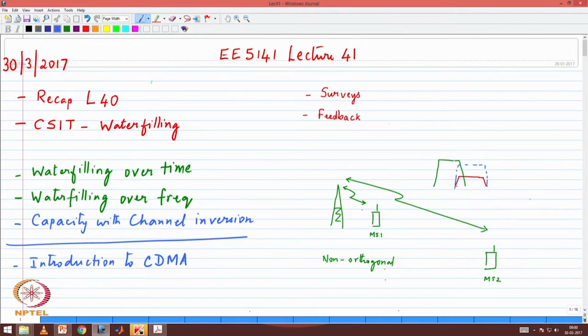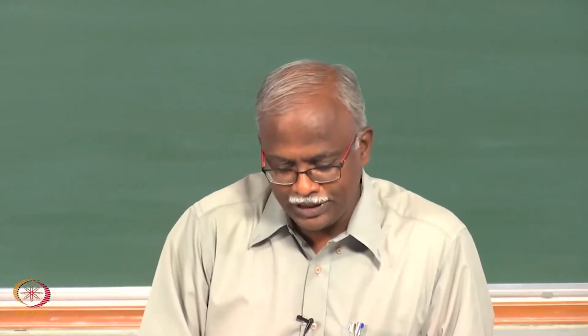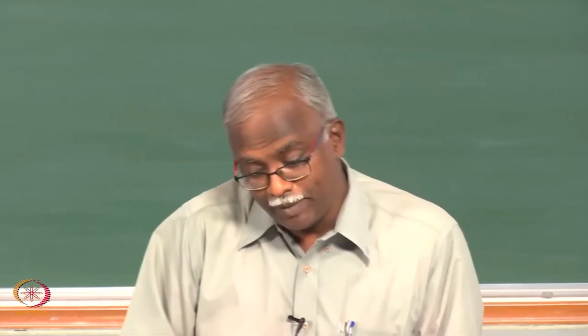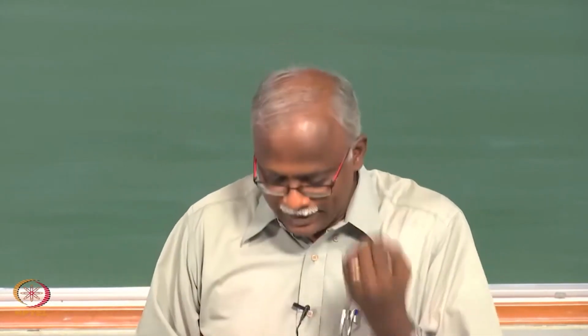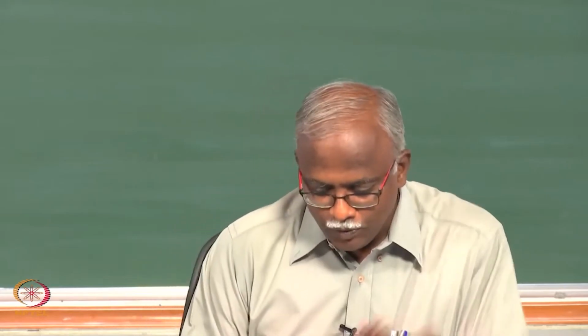Okay. So loss of orthogonality is very, very important when we talk about different users, and one such situation arises in CDMA, because in CDMA both are using the same frequency, and if for any reason there is a loss of orthogonality, then they will interfere with each other. So for this purpose, there is a requirement in CDMA which says all the mobile stations ideally should be received at the same received power.